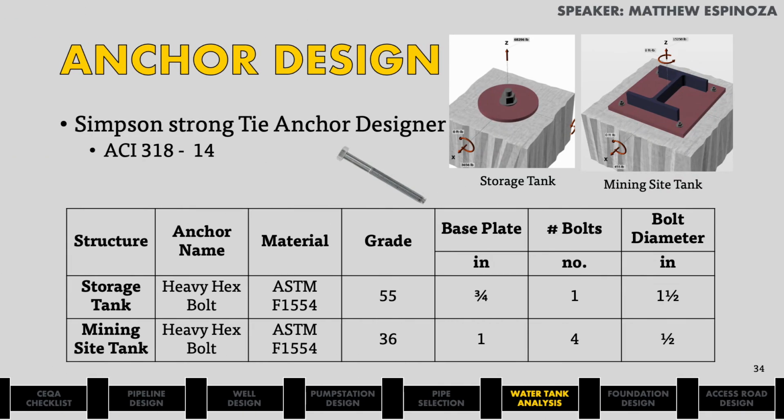My name is Mach, and I will be responsible for the anchor design for both tanks. The anchor bolt design was referenced from the Simpson Strong-Tie Anchor Designer software, following the American Concrete Institute standards ACI 318-14. Information was provided by the SAP2000 analysis for both tank designs. We used the maximum uplift and shear force, which calculated the best overturning and sliding resistance.